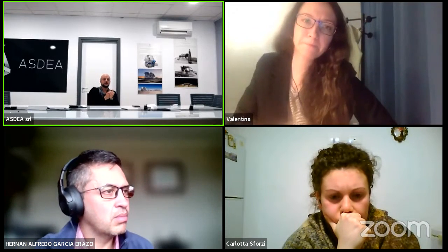Okay, so if you create a small gap, and I explain it in the webinar about contact element, then I will be able to compute the distance from the slave to the master. And so we'll be able to compute automatically the contact direction. And then optionally, you can say that this initial gap is rigid. Okay, so it's not a real initial gap. So if you look into the webinar, try to look at the options from link direction and initial gap. Those are the two options that you need. The only problem for you is that you need to refine your model a little bit because you need to create a little gap between the shell and the beam. Okay, it will be much easier than creating a lot of different local axes, for sure.